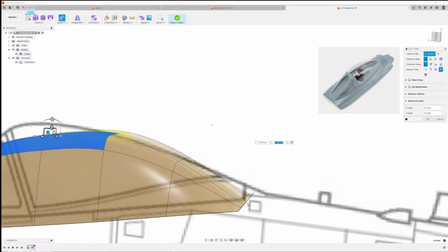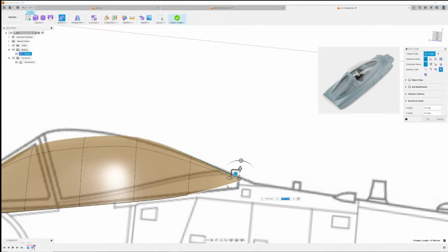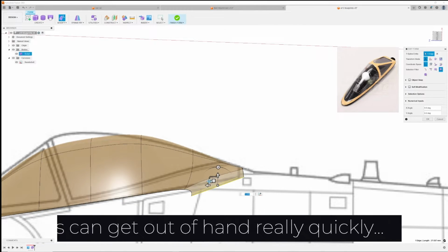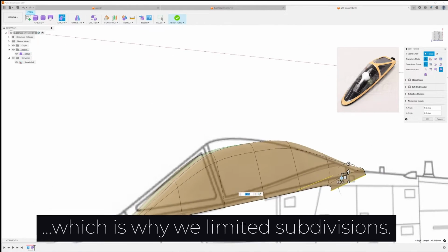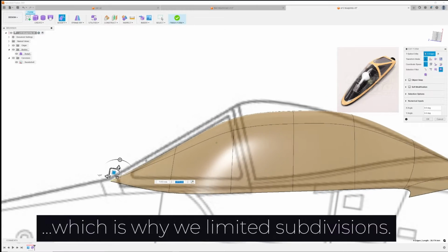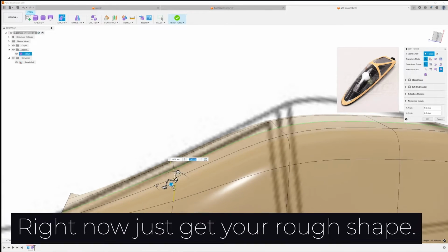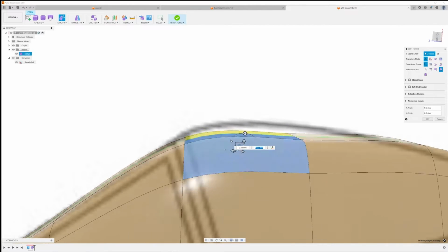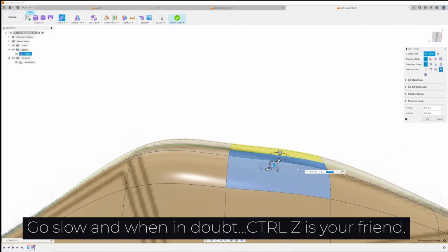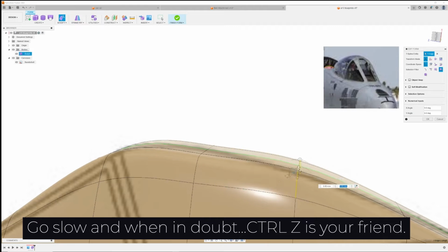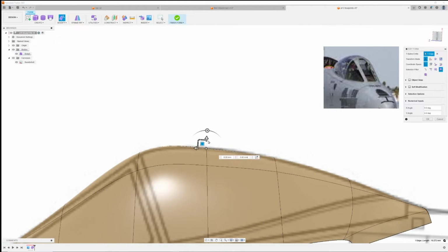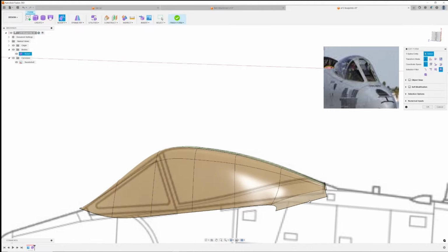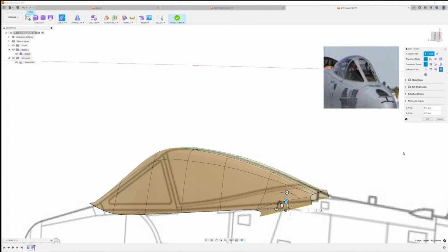To bring up modifiers for our Forms plane, right-click and select Edit Form. A new set of modifiers will appear allowing us to modify the plane. These modifiers are similar to the modifiers from the Move command with the exception of the small lines surrounding the square box. These lines allow for expansion and contracting selected parts of our plane. You can select faces, edges, and vertices on the plane to modify. Because we've made our plane symmetric, I'm starting with modifying half the faces and aligning them with the plans.